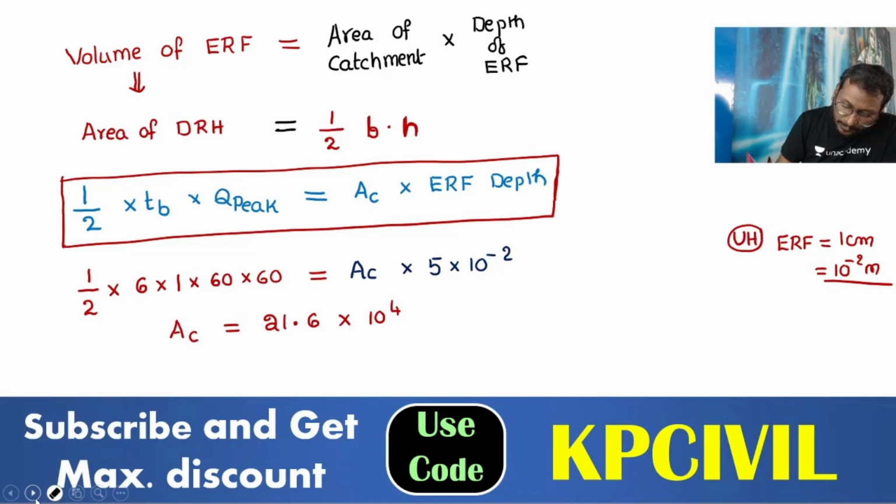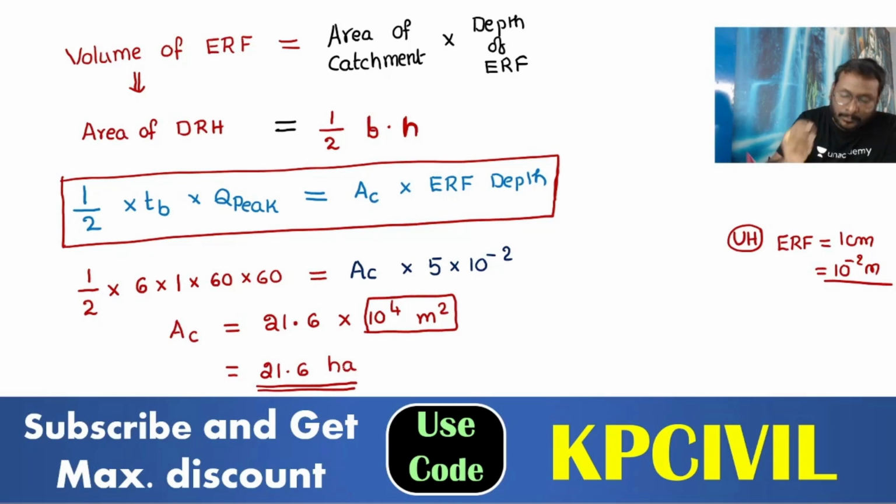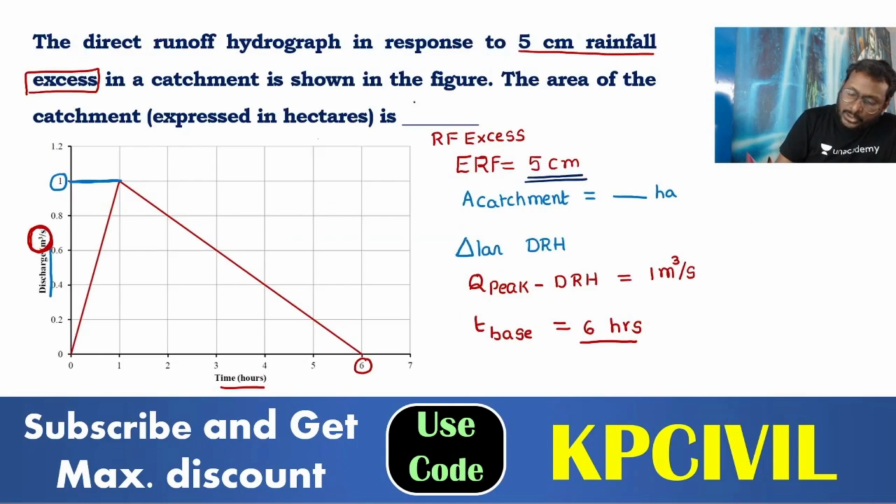21.6 into 10 power 4 meter square. 10 power 4 meter square is equal to hectare. So we can write it down, 21.6 hectare. This is the answer now. Area of catchment is 21.6 hectare.